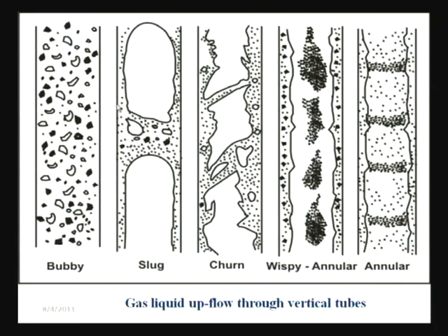In this particular case there are a number of interesting things. Firstly, there is the periodic flow phenomenon. Secondly, if you observe slug flow, you will find that there are regions where the liquid is flowing downwards and regions where the liquid is flowing upward. So, if you notice the wall shear stress, you will find that it keeps on changing direction with the passage of the bubble and the liquid slug.